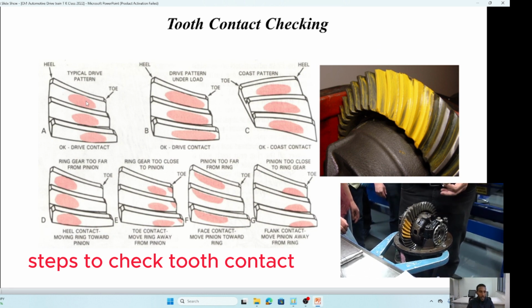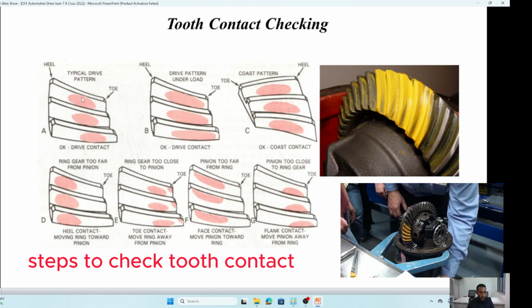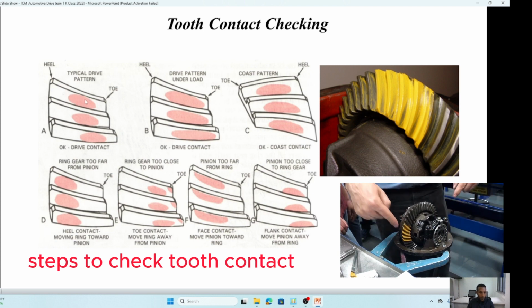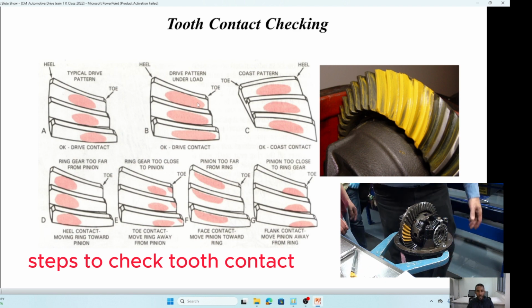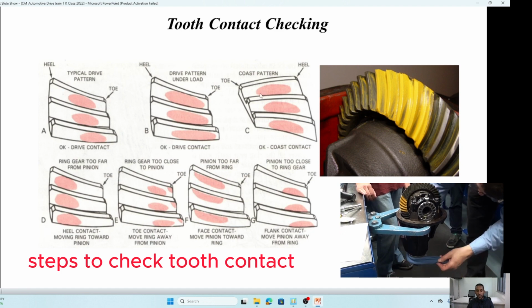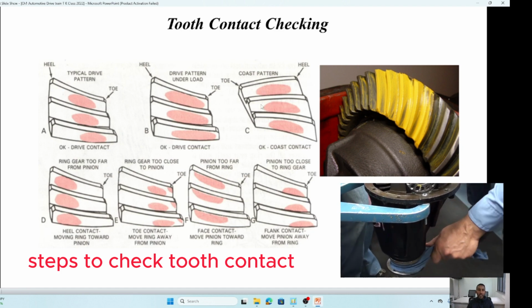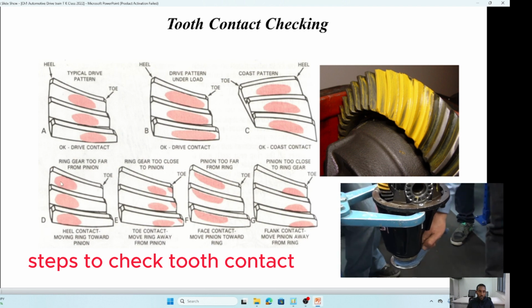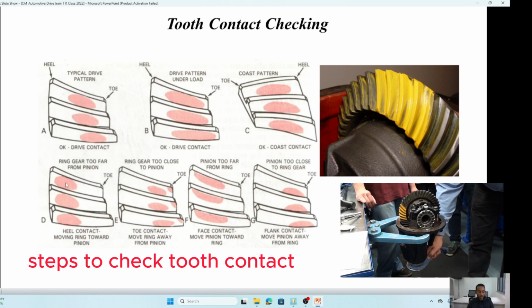If you look at this gear, the contact area is mostly at the center, but at a lower surface area. Okay, it's okay. Also, if you observe this one, a little bit wider contact area, so there will be enough load distribution. Again, it's okay. The third one is also somehow good. It's a little bit bottom, but still it surrounds the center part of the gear. But if you observe this part, most of the pressure is at the rear. We call this heel contact.